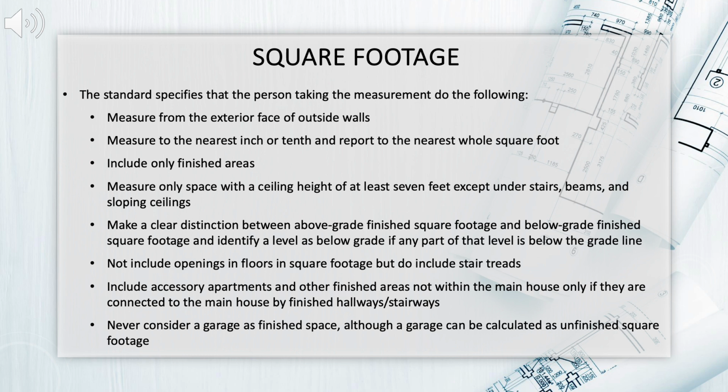Square footage. The standard specifies that the person taking the measurement do the following. Measure from the exterior face of outside walls. Measure to the nearest inch or tenth and report to the nearest whole square foot. Include only finished areas.